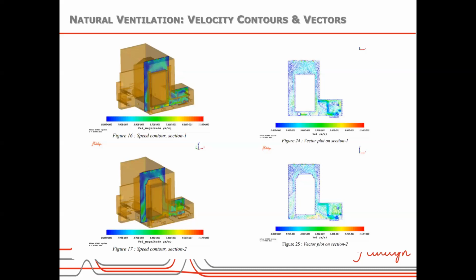That set of boundary conditions makes the results stable, and we get steady results, particularly in natural ventilation. In forced ventilation it's not a matter, and we can get convergence very fast. But in natural ventilation, it is very important to specify the outlet open conditions.